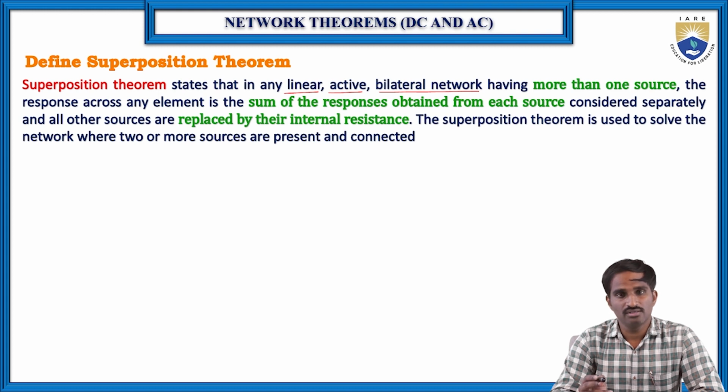Then the response across an element in the actual circuit is equal to the sum of the responses obtained from each source considered separately. So this is the statement of the superposition theorem.